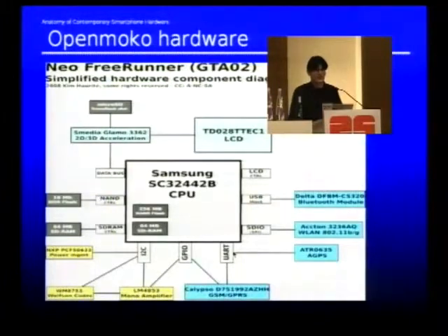But it makes me extremely worried if the GPS is connected to the baseband side. Then how should I trust the device? The GPS data first goes into the GSM modem, where all the deep secret GSM stack is running, and then the GSM data is forwarded to your application processor. So if you switch it off on the application processor side, is it really switched off, or does it still feed the location into the GSM modem?